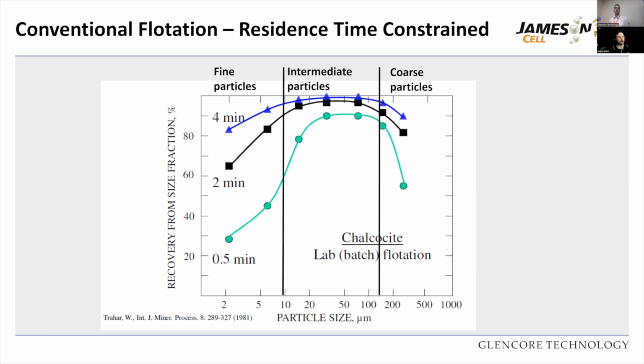So this is just highlighting a chalcopyrite float in the laboratory and the impact of residence time on recoveries of the target material. So as you can see, particularly in the fine and coarse end zones, at only half a minute, the recovery is very low of your fine and your coarse material. But your recovery improves through all the zones as you float longer, which clearly makes sense in a mechanical cell. The longer you float, the more time you give for it to recover material.